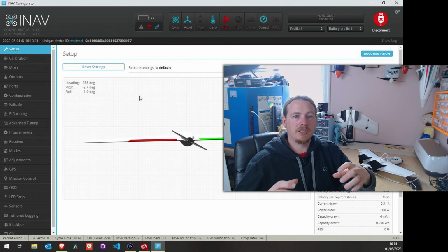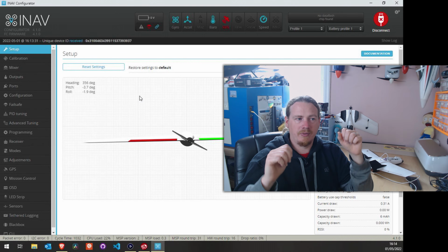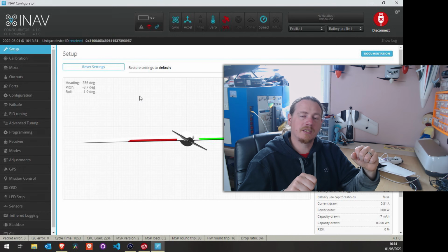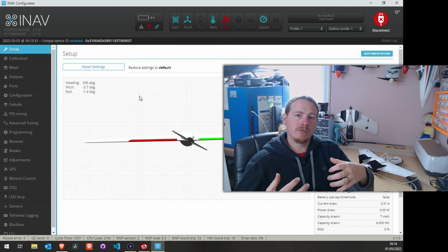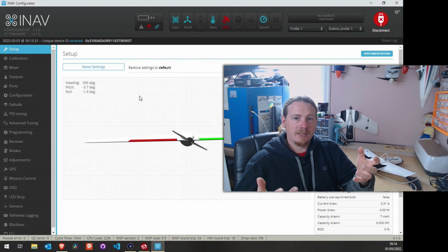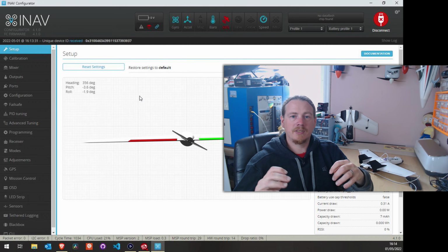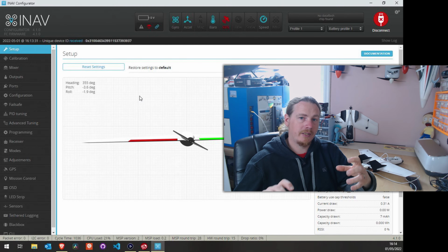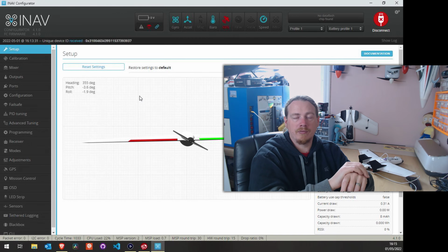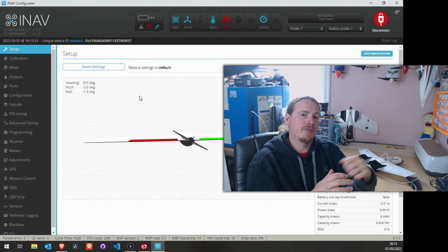If you find that the launch isn't working well and you're having to shake it to get that bit of thrust, this is when you should be using idle throttle. And you don't need to go full throttle with it, or you don't need your full launch throttle. You just need enough to give you a hand to keep the plane straight and give you that bit of thrust to get the plane in the air for the detection.